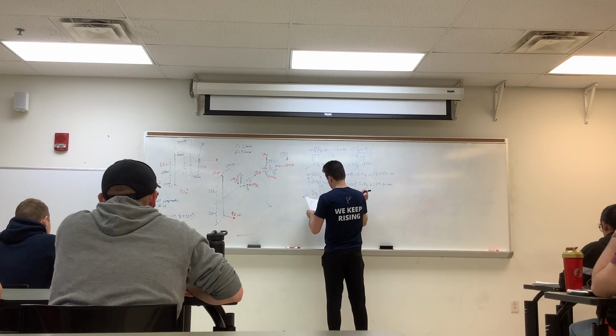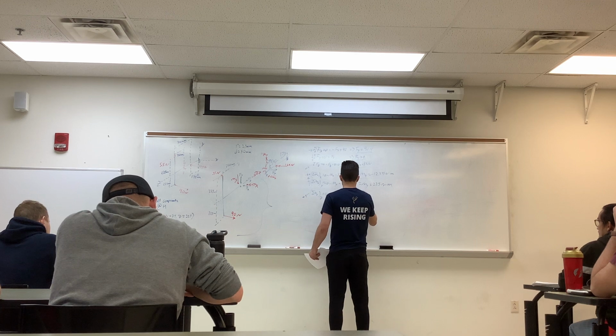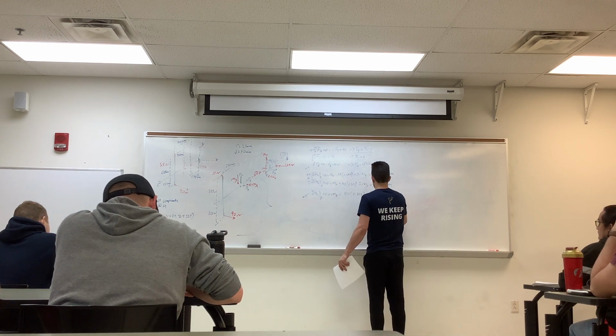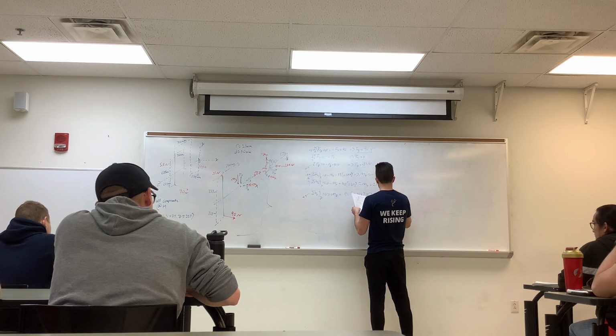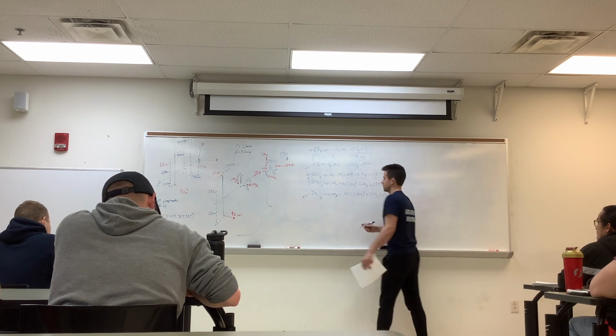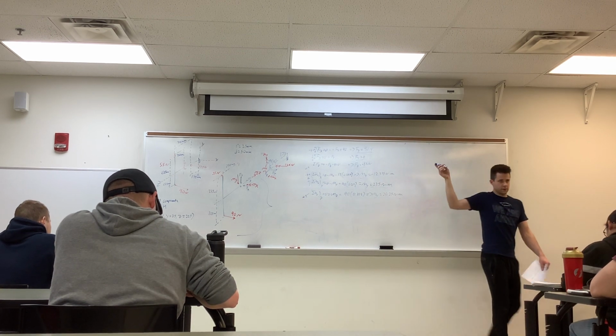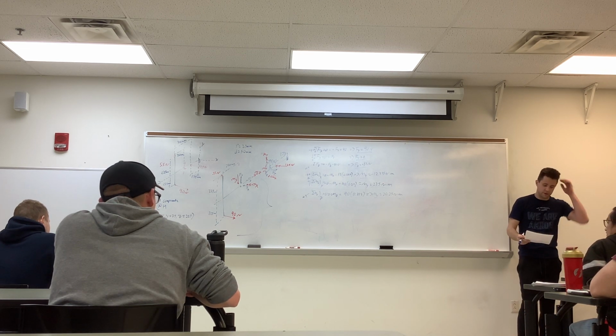And it is positive in this case, so 90 newtons multiplied by that moment arm, which is 0.225, giving us our moment to be equal to 20.25 Newton meters. Any kind of questions with any of this, or the right-hand rule, everything that goes with it, to find all your internal forces?